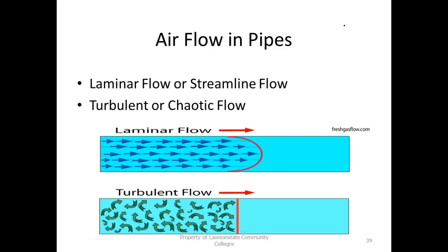So in fluid power, we use valves, just like your faucet. Your faucet is a valve. And what can you do with that? You can turn it on or turn it off, and we have what we call proportional control valves, which unfortunately we don't have any of those here, which you could actually control the flow, right? How fast things move. All ours are going to be what we call digital. They're either going to be on or off or left or right, and we'll talk about that. So what we do with these valves is we can either cut it on or cut it off, right? You understand? Or we can control the direction, which means if I'm going to move something left and right, then I got to put pressure. I got to have some way of swapping which way the pressure's on.